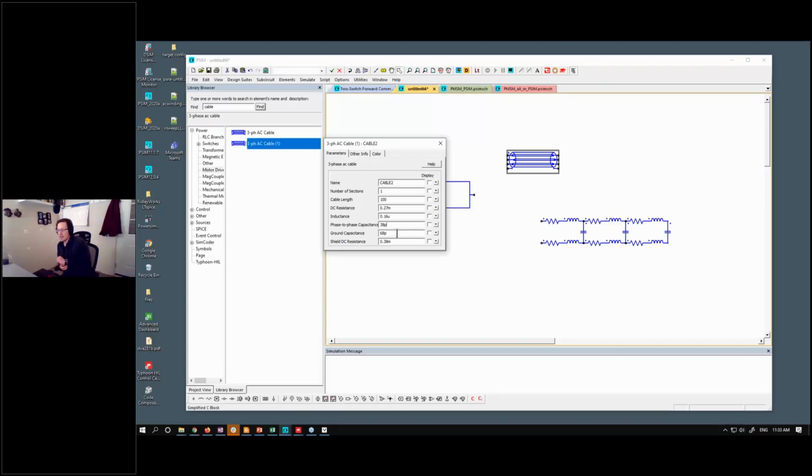Very stiff state-space matrix equations are not an issue with PSIM because we're not using state-space matrices. We're doing a nodal solve at each time step. We solve the full simulation without any interfaces, so that's not an issue.